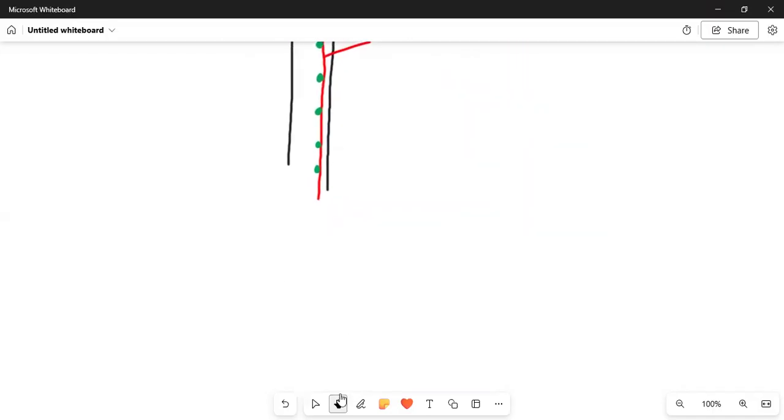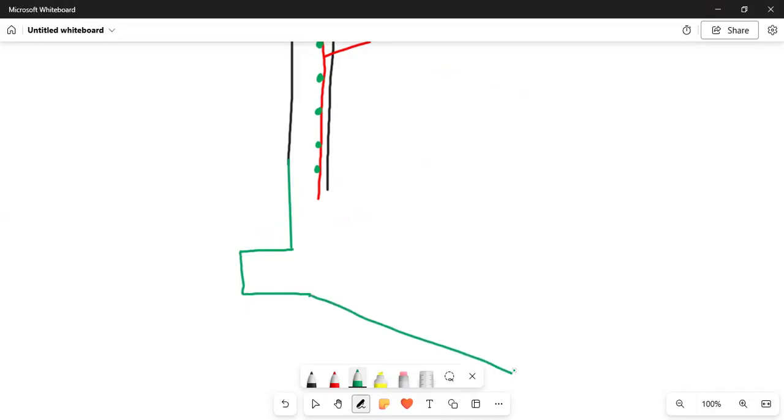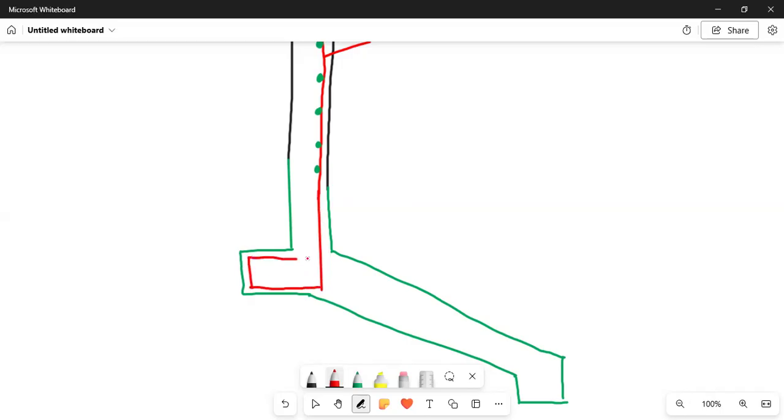Now we'll see the detailing of the hopper part. So the hopper bottom will be like this. This will be your hopper bottom. Here you have the edge beam. You can continue this part, you can take it up, and here you have a beam. You can join this to the beam. Then from the beam you have another reinforcement in the direction of the sloping slab.